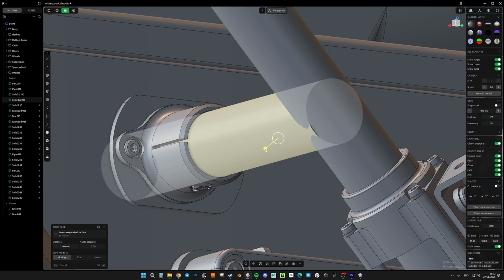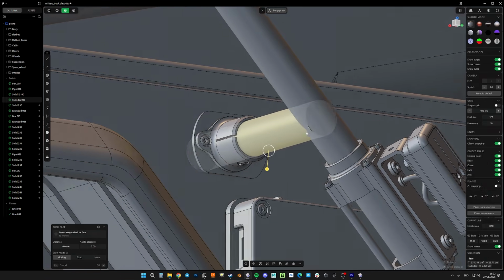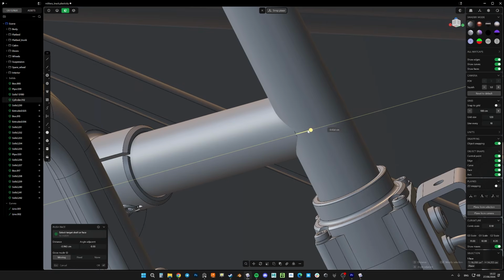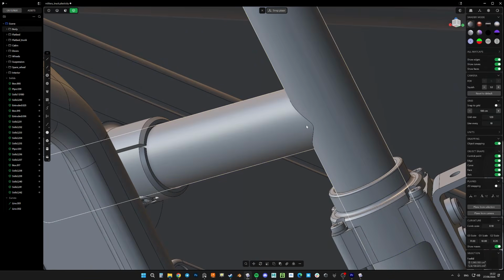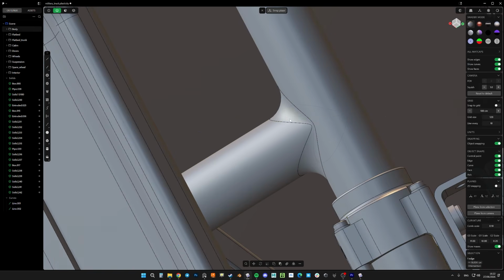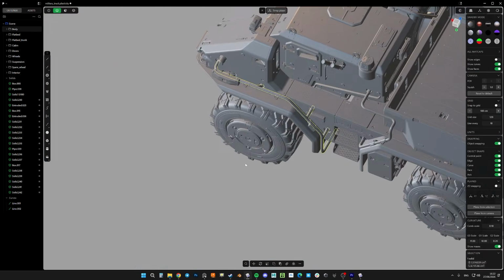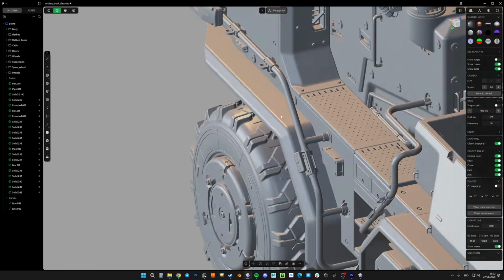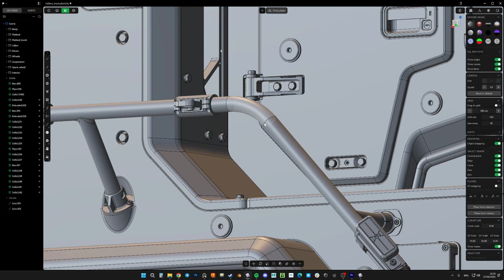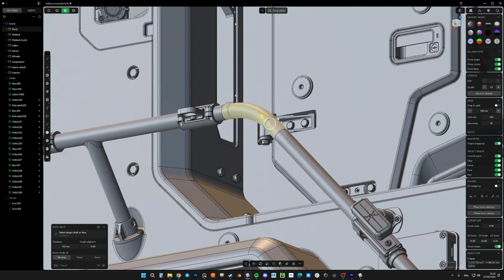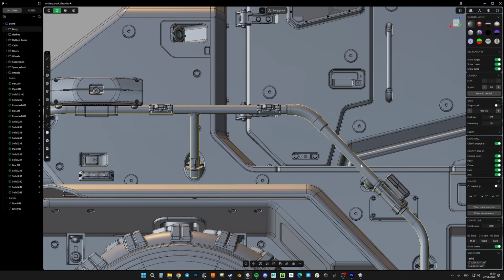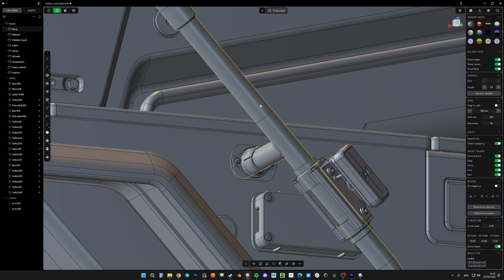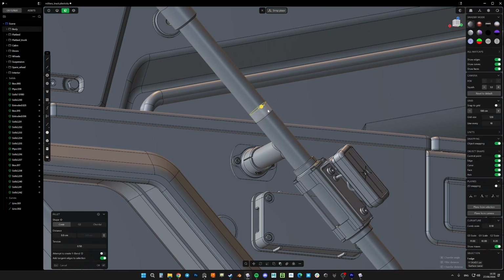Usually I make it a bit less of a radius than the original, so it perfectly goes inside. Then you just pull them together and create a fillet. For something non-standard, you can always use the param tool to extrude shapes and make thickness variation easily to make it look cooler and interesting.